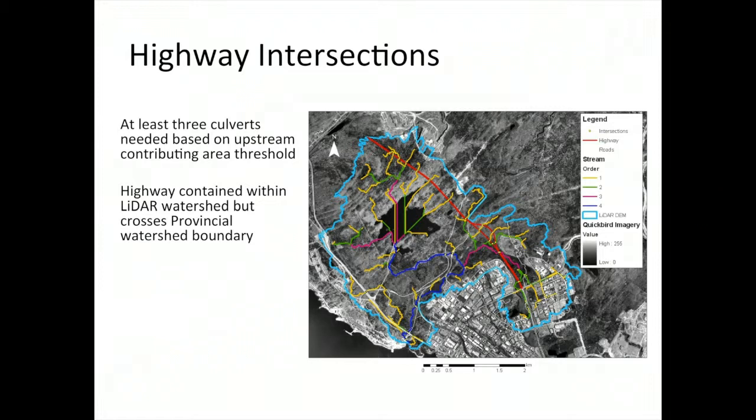Well, you can kind of see them. Anyway, the point is we can map and quantify where those crossings are, and those tell us the potential culvert locations for that new highway development. And, you know, should we put a culvert there, or should we just route it down and collect multiple crossings and route them to one crossing? It becomes a very easy analysis if we have the high resolution DEM available to us. If we have to do it in the field, it's not such an easy analysis.